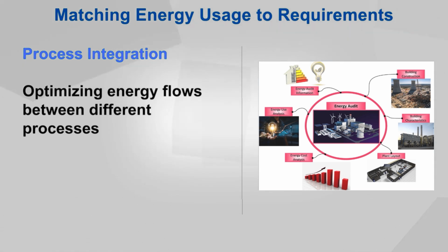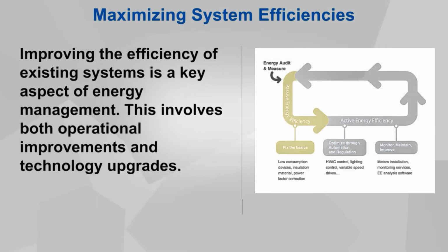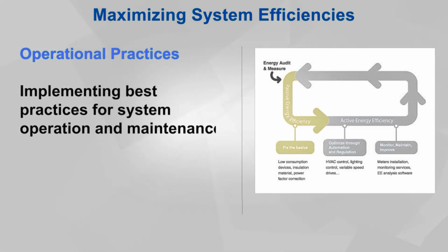For fans, we can eliminate damper operations by similar methods: impeller trimming, installing variable speed drives, modifying pulley diameters for belt drives, or resizing the fan for better efficiency. In processes which require chilled water, moderating the water temperature to align with the process needs can also save energy. Additionally, recovering energy lost in control valve pressure drops by adopting back pressure turbines can further enhance efficiency.